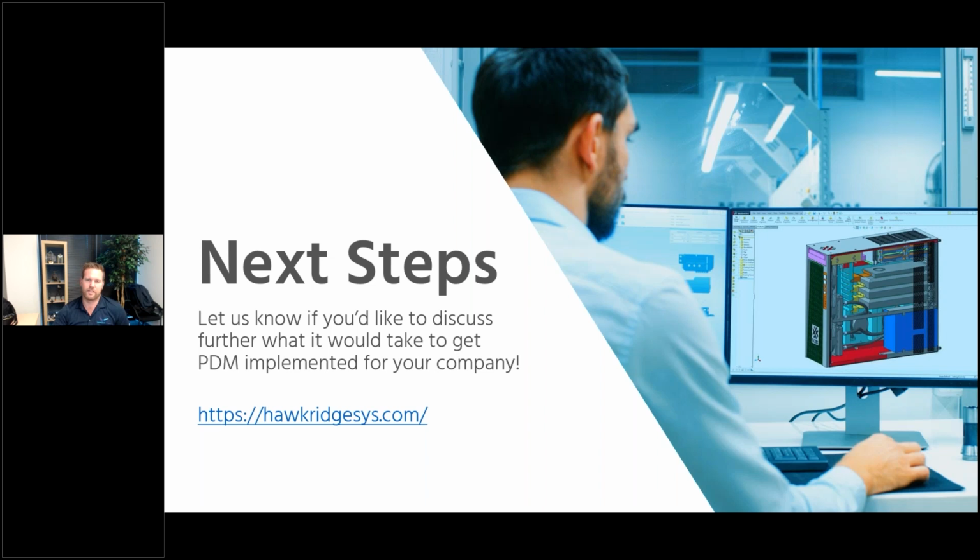And once those are all set up to map appropriately to the file that's saved inside of PDM, you essentially just create a BOM in the admin tool and designate which columns you want to include in it. And you can create different variations of that, which people very often do. If they have built or purchased components, you can use that to filter them out or include or not include specific columns for that BOM. So it's just making sure that it's set up correctly, and then it's just a simple single click in PDM to export that as a CSV or Excel file.